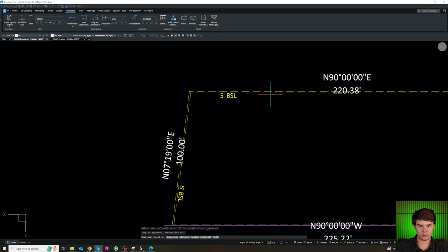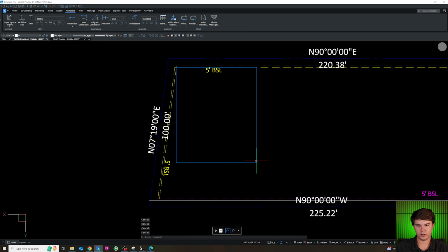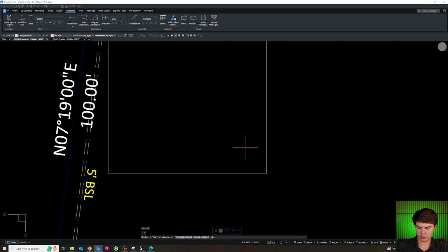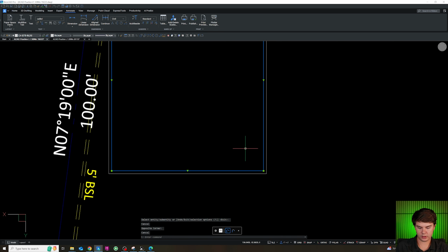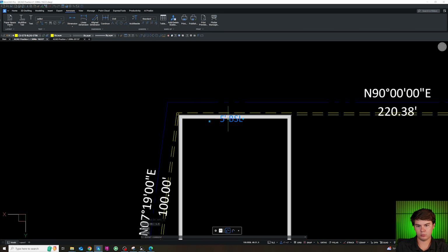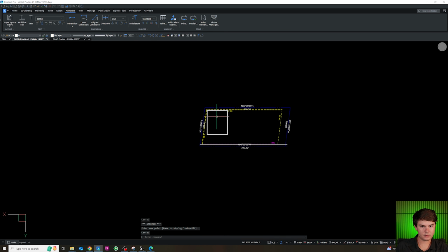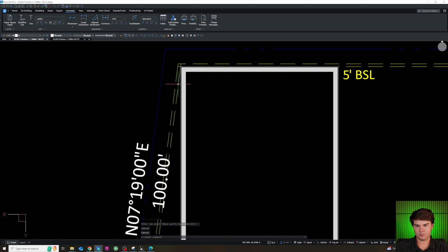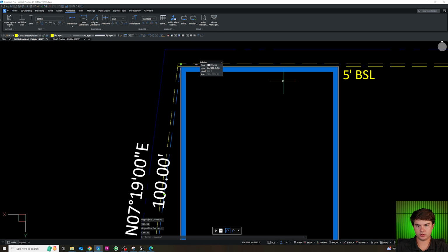We're going to have a 54 foot wide and 64 tall building. So here's our building. Go ahead and put it on the building layer. Offset it 1. Set polyline width to 1.5. Here's our building. Move this so we're not in the way. Delete our constraint lines.